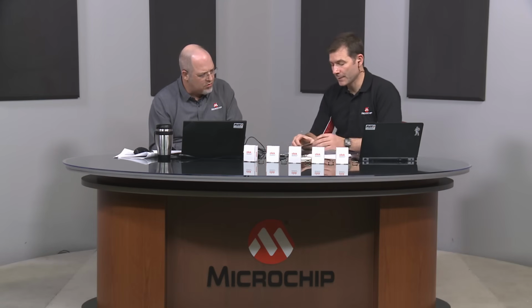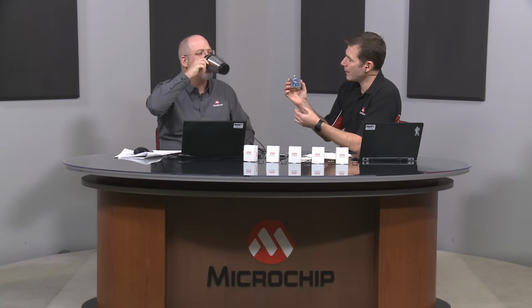Yeah, I can. The first one we have here is one of the Xplained boards. This is an Xplained Mini board where you have a built-in programmer and debugger on the board, and of course the target device. In addition, you have a few touch buttons here. You have to add the software for that, but you also have a lot of prototyping area where you can add components, laid out so that it can match specific standards. For instance, the Arduino standard would fit well with this one. You have that marked out where you can put the headers in, and then you can put an Arduino compatible shield on top of that.